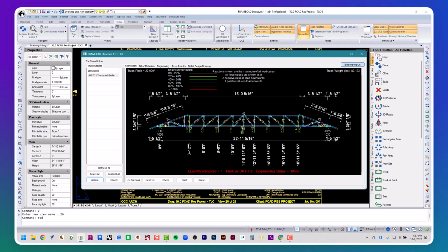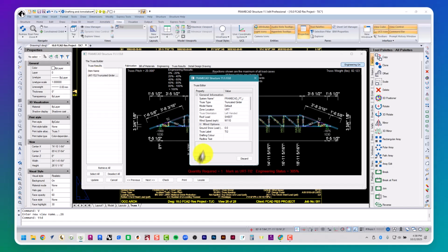When we initially adjusted the last truss, we edited the spacing, so this time we will focus on changing the material of the truss and reinforcing the top and bottom chords instead. First, list the truss from the truss results list by double-clicking its name on the truss results navigation pane. Scroll down to the material selection.